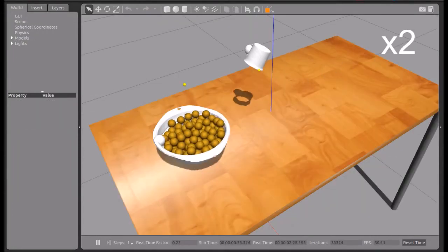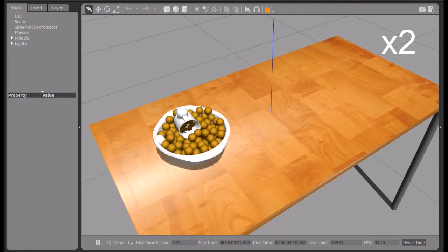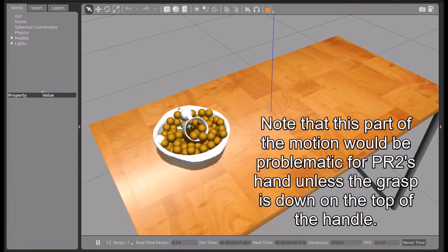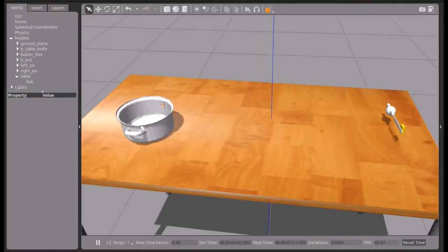Next we will see how the system autonomously adapts to use a mug in the wrong initial orientation. The vision module fits a superparaboloid to the container of the mug and therefore knows the correct orientation. Once again, the scoop action involves rotating the ellipse of the mug opening horizontal and lifting. Note that this scan mug had some holes due to the difficulty of scanning those areas. Finally, we briefly show the scraping and cutting tasks adapted to different tools.